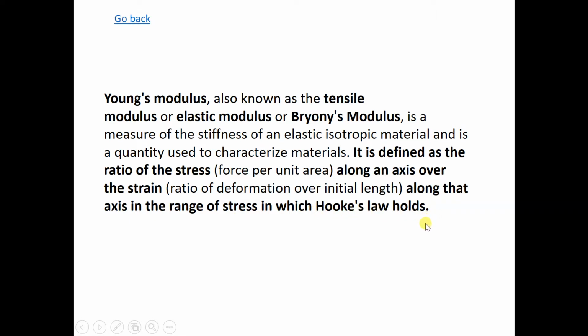So we look at the figure. It's linearly elastic, for the value of stress over strain. When you apply the load, the stress will be proportional to the strain, and that means that when you apply loading, the expansion or the compression will be proportional to the stress. But when you remove it, it will go back along the same linear line and then back to zero. So there's no deformation.